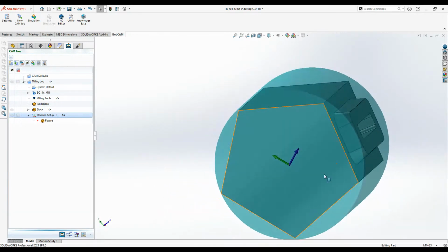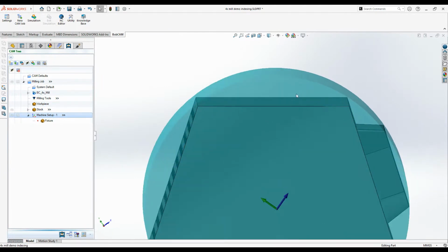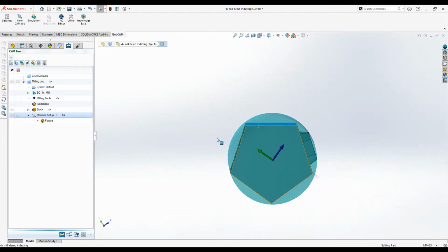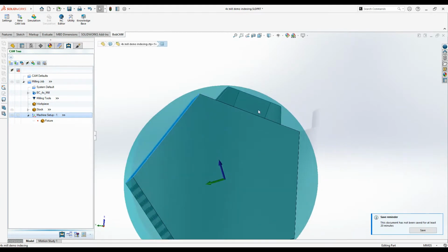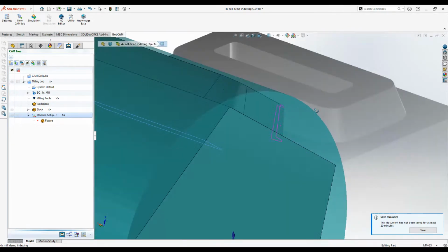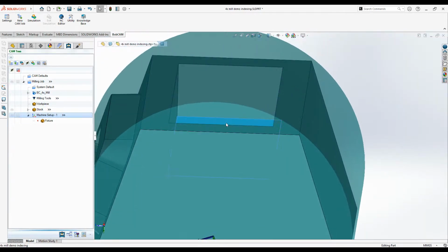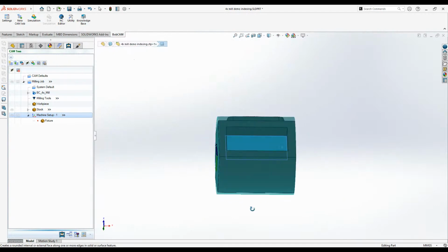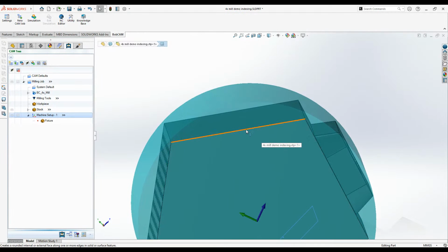So to rotate around this way to get to here, and just use a flat end mill for a facing operation very easily there. And then rotate around, do a 3-axis milling operation to get all the way down inside of the pocket here. Go around and do the facing and the pocket operation. And so to rotate around and lock the rotary axis to this location, again, we can create an index by